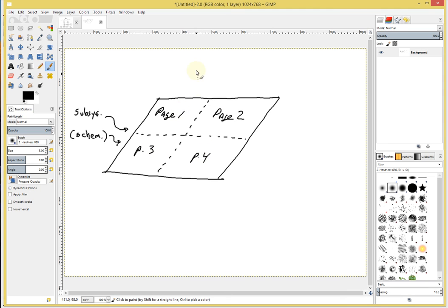side by side. The way that you connect a component or a wire from this schematic to another page is that you use what are called off-page connectors, which is indicated by this symbol right there. And this connects to another off-page connector on another sheet. And the off-page connectors are specifically for this purpose. So, going back to Capture,